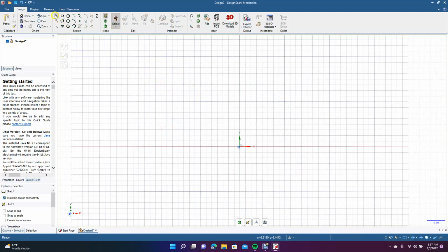Okay, now we're going to come up here to our actual tools. We have a line tool, and with each of these sketch tools, you also have a few options down here in this dialog box. I don't typically use a lot of these. You can define from center on most of these drawing tools, or you can turn on the snap to grid. Sometimes I turn on snap, and sometimes I use define from center, but not on all of them.